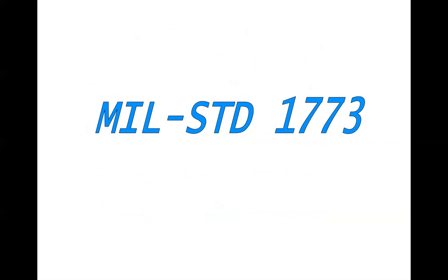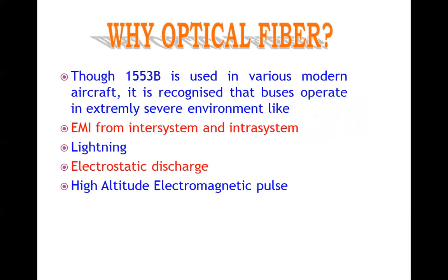MIL-STD-1773 is going to be seen now. Why do we go for optical fiber? Though 1553B is used in various modern aircraft, it is recognized that buses operate in extremely severe environments like EMI from intersystem and intrasystem, lightning, electrostatic discharge, and high altitude electromagnetic pulse.